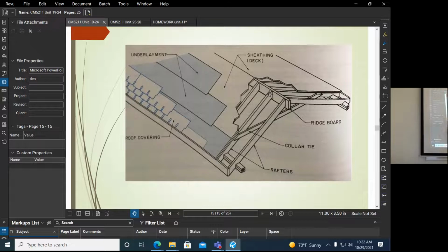So we now have some materials for our underlayment which will protect the underlying roof, and which is more compatible with the tile roof system, because a tile itself, a concrete tile, will last 100 years. But if you have the paper underneath failing every 20 years, that's not an effective use of your materials, because you have to keep pulling it off and reinstalling the underlayment every time that fails. So 15-pound will definitely fail within 30 years. It kind of defeats the purpose of the 100-year material, and you have to keep dealing with it.